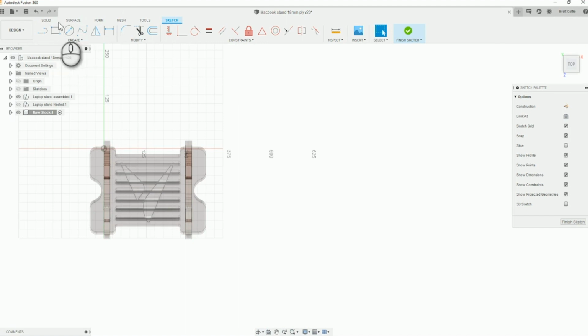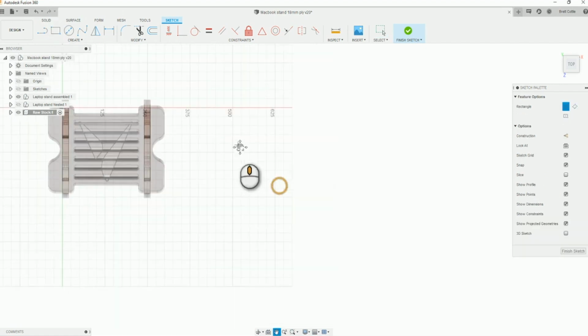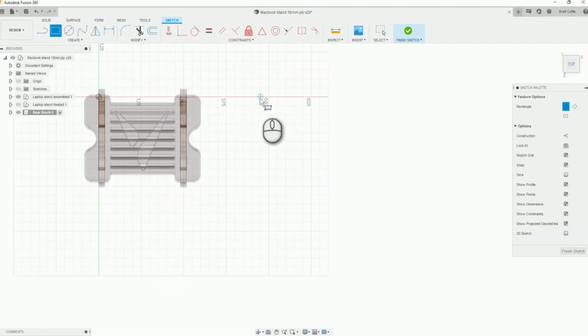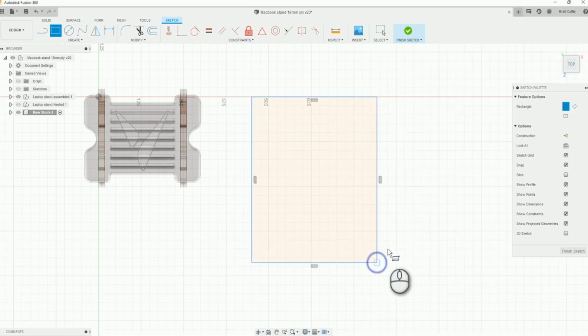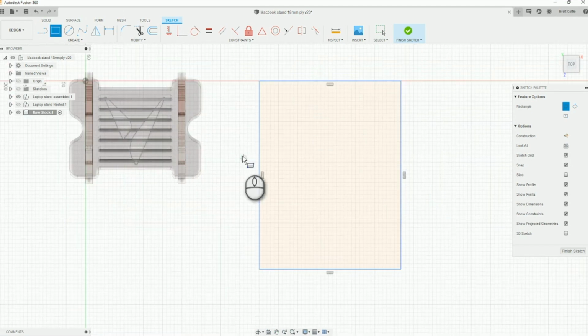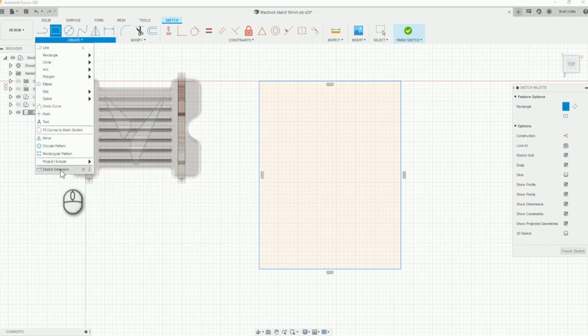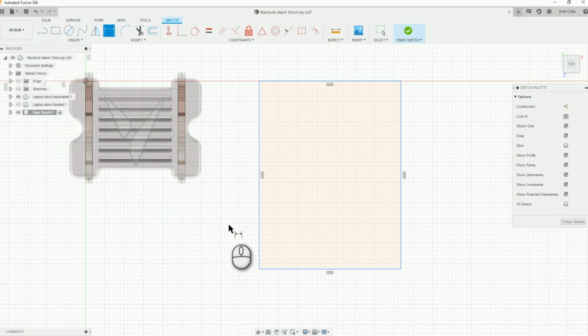Now our sketch tools have shown up. So I'm going to grab a 2-point rectangle, click that once, come down and snap to the red line, just anywhere, and drag out. Now I'm going to come in and dimension. Remember, you can come down to Create and click the sketch dimension at the bottom. Whenever something has a capital letter next to it, you can use hotkeys, so you can hit D on the keyboard. If I hit Escape and go out of that, then hit D and select any of these lines, I can now dimension that line.